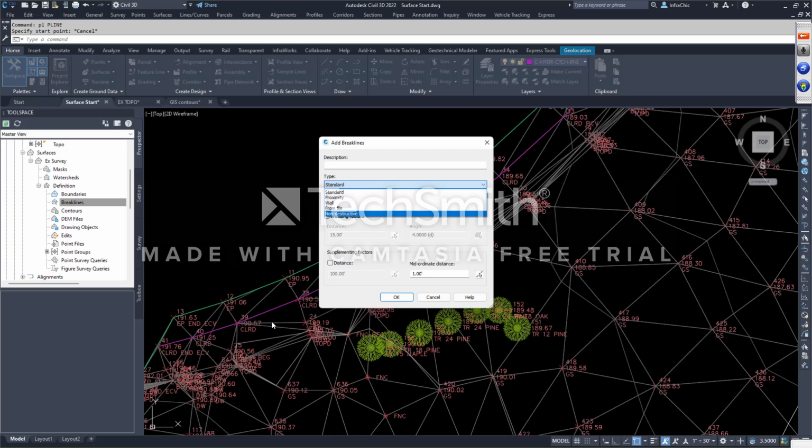If I say this is the top of the wall, we're going down, you know, we lose 4 feet. Again, every shot here going the direction I say that the wall goes down, offset -4. The problem I have with wall, and it works well in most cases, other than the fact most walls at the top are very smooth and flat and do not reflect jaggedy, jiggity jogs that are actually in the surface.